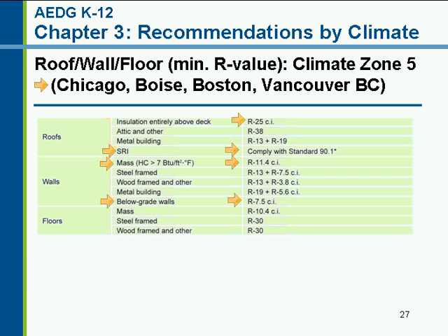Continuous insulation can be easily installed on the outside of the building, with the earth backed up against that. That gives you lots of flexibility with how you finish the inside of the below grade walls. Make sure that you carry that up to cover any of the basement walls that go above grade. So maybe you've got 6 inches or a foot above grade.